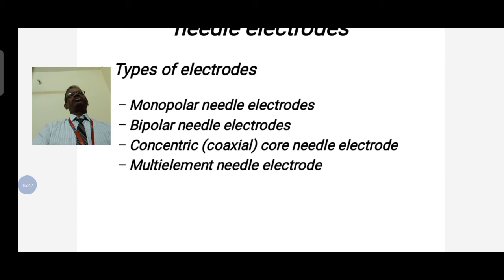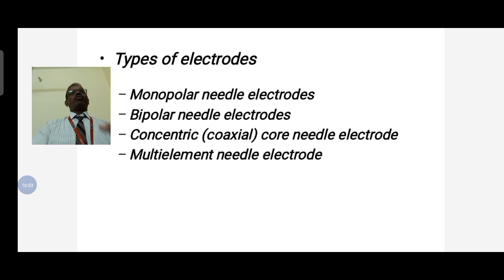These electrodes pick up mostly microvolt signals, which are not visible. So the signal is converted using an amplifier, a bioamplifier. The bioamplifier converts the small microvolt signal to a large signal, which is given to the signal processing unit to analyze the signal.